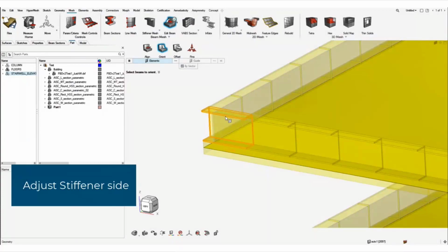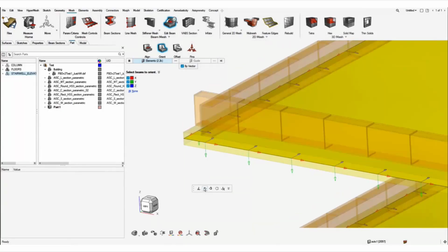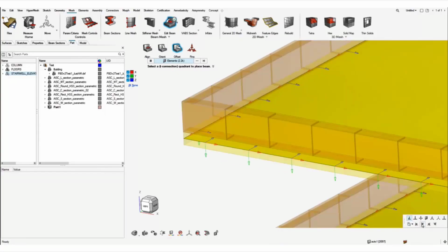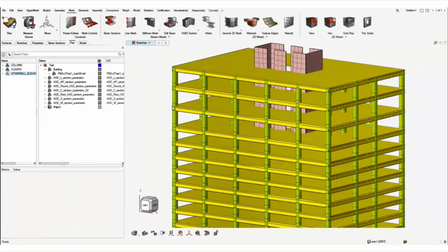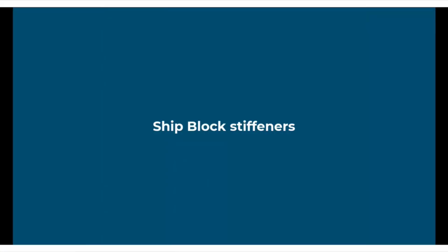Just that here, by default, it goes on the shell top side. So if I want to have a stiffener below that plate, I can basically reorient it by 90 degrees. And we will re-offset along the shell positive normal in this case. So here we have several options to, let's say, reset to shear center, position at origin, or position on top or bottom of plates. And here we are done with this case.